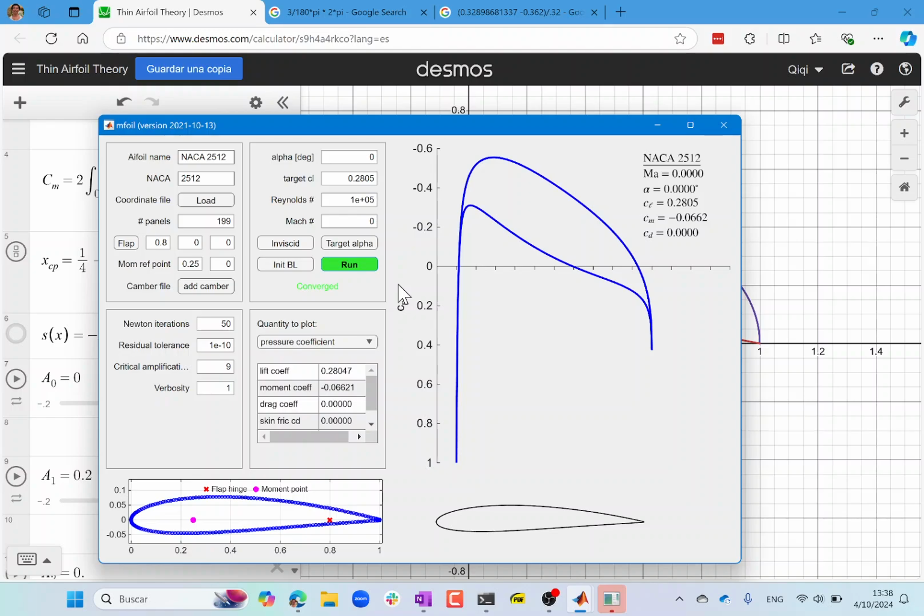Okay, now look at your screen. The Cl I get is 0.25, and the Cm I get is minus 0.066. Right? If you multiply 0.066 by 4, it's 0.26-ish, right? So that's 0.25, 0.26-ish. So that's actually getting close to that Cl. What angle of attack? Zero angle of attack. Oh, okay. Yeah, that's what we looked at in class today.